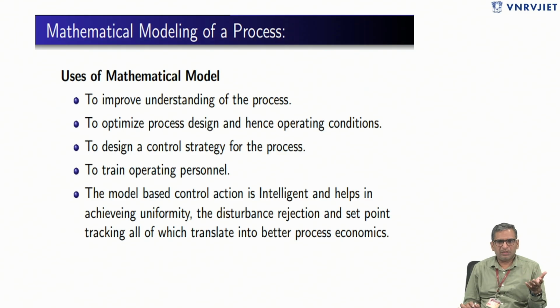Similarly, here in process control instrumentation also, if we have a model of a process, that model will help us to understand the behavior of that particular plant. Similarly, we have some advanced control schemes or model based controller approaches like internal model controllers, or model predictive controllers. Like MPC, IMC, these types of model based controllers we can design if we have a good model. So we can call it model based control.